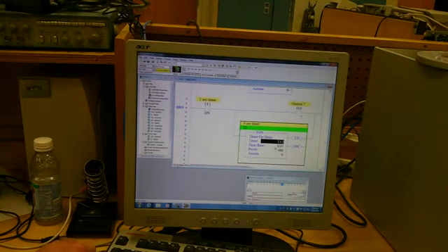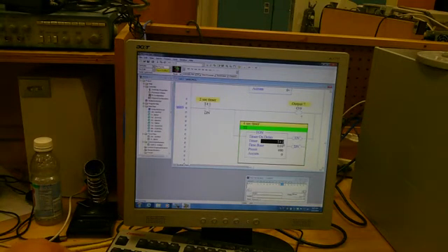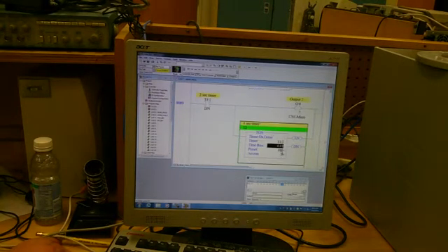Why did you do that? Do what? Take the time base down to hundredths. Because why do the same thing over and over again the same way? That doesn't make any sense, right? So we can use a hundredths time base. Now we can't use the thousandth. It says we have a thousandth one, but in the MicroLogic 1000, there isn't such a thing. So that would come up as an error.